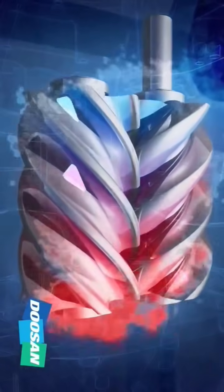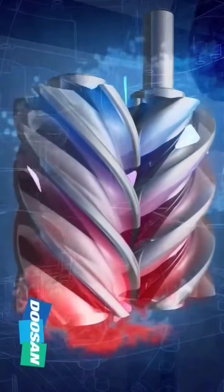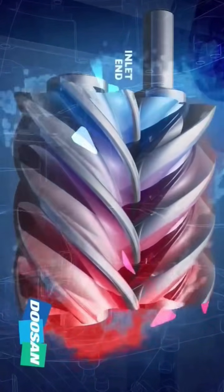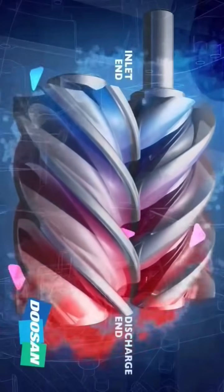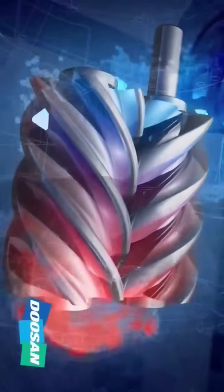As air travels along the helical rotor flutes, the space storing the air gets progressively smaller. Since the air cavity between the rotors is larger at the inlet end and smaller at the discharge end, air becomes compressed, creating significant heat.